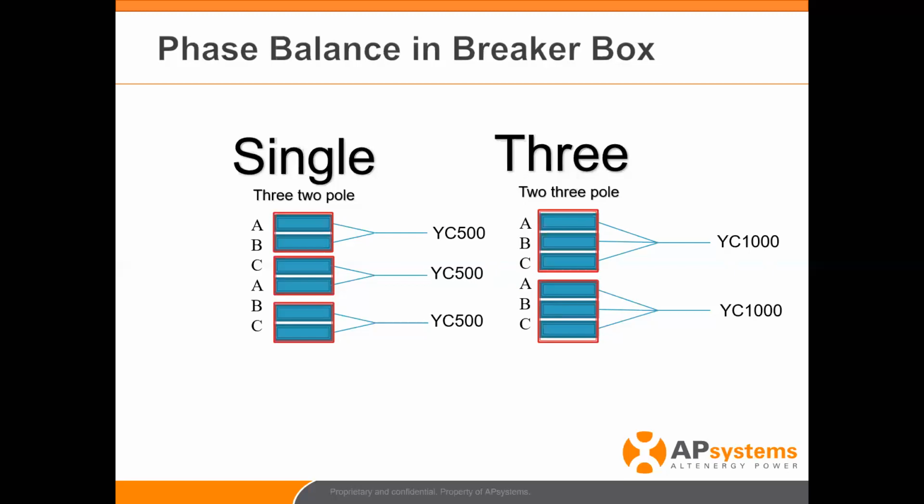So just be cautious when you're sizing the system. Don't always size it based on nameplate rating, because the nameplate rating is something you're never going to reach. I like to use the analogy of the gas mileage sticker on a brand new car. You look at the sticker on the window and it says you're going to get 32 miles a gallon. That's tested in perfect conditions, with beautiful tires on a flat driveway with a slight incline and a breeze at its back. So look at those things.